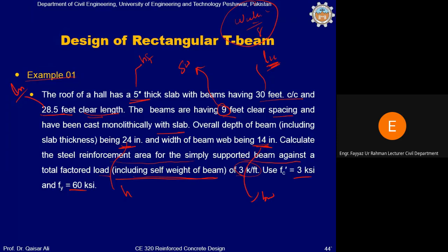तो फर्स्ट स्टेप क्या होगा? In the first step, since you can see that in a simply supported beam the flange will be in compression because it will be subjected to positive bending moment। तो इसका मतलब ये कि you have to first calculate the effective width of the beam। Effective width का मतलब क्या है? This is basically that portion of the slab which is effective in resisting the compressive stresses। तो ये आप कैलकुलेट करेंगे।